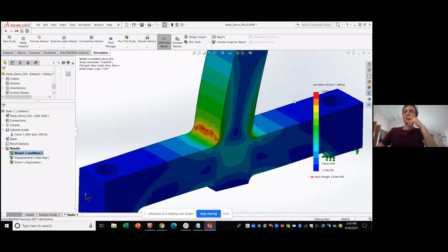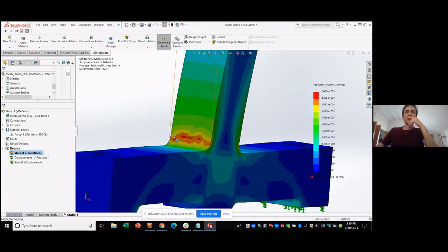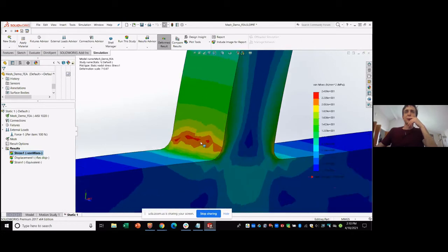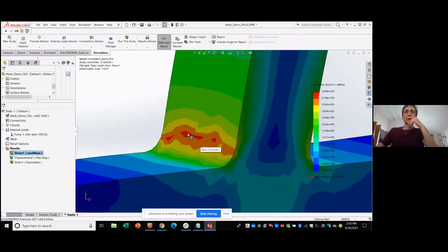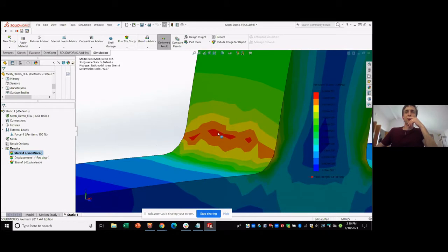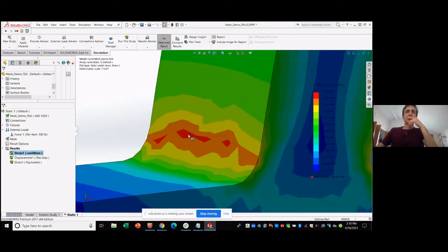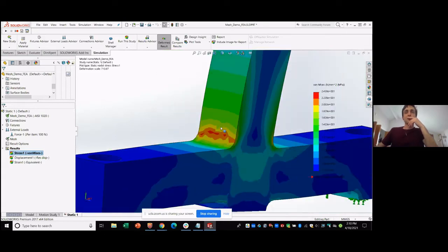Probably not. We would expect that the peak stress would fall more or less uniformly along a continuous line here. And you really have no idea whether this is realistic or not because it only occurs at a single point. And it's very obvious that that is influenced by the coarseness of the mesh.